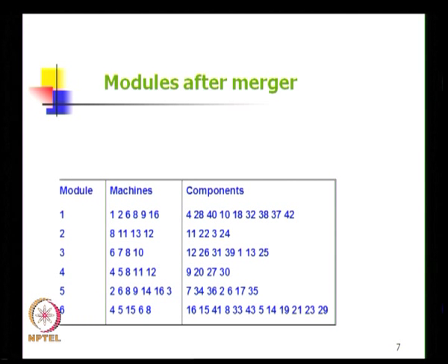Now, let us quickly look at it and say we need 6 machines here, 6 plus 4 is 10, 14 plus 5 is 19, plus 7 is 26, plus 5 is 31 machines we require to make this, and we have 16 machine types. Now, we have to go back and see whether we actually have, since each machine type can have multiple copies, enough machines to create this.